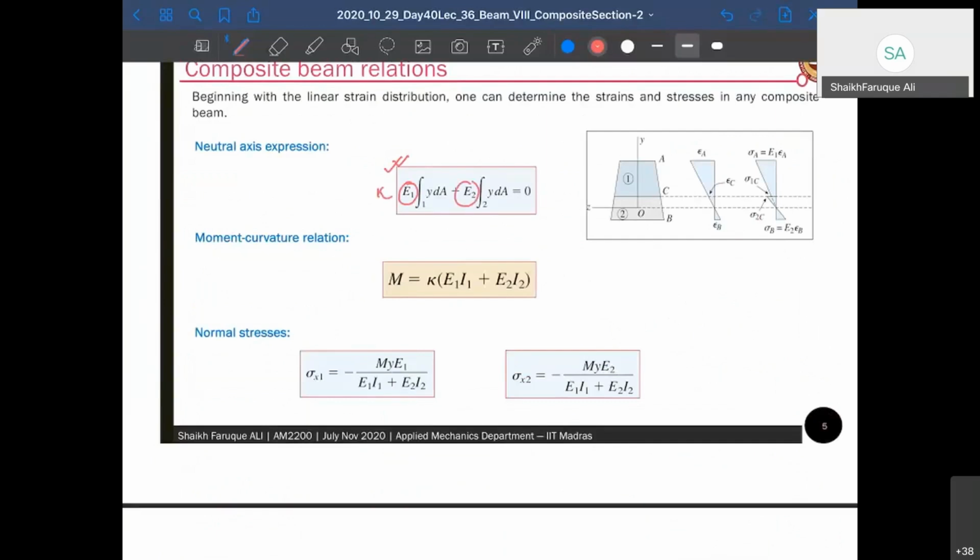So kappa into E1 into dA was the force, sigma x, at a small location, right? At a small location like this. And when you multiply with y, and integrate over some range, you get...